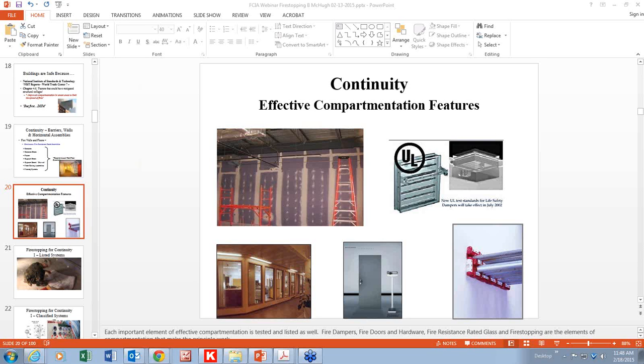And the reason is that the L-rated Firestop system has a quantifiable resistance to smoke that's been tested to UL 1479. The test standard wins in the court of law as to the suitability of use statement for the product used in specific applications, whether it's water resistance, fire resistance, adhesion testing, cohesion testing, whatever it is.